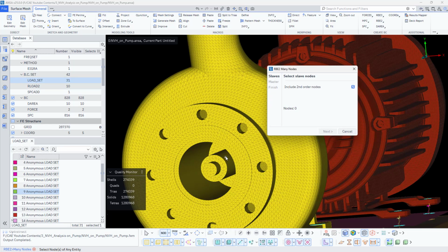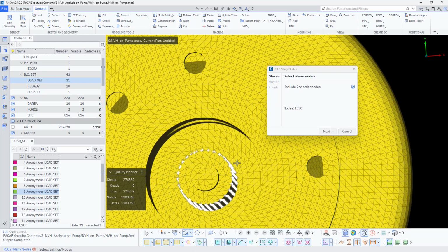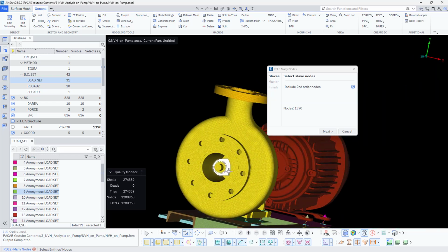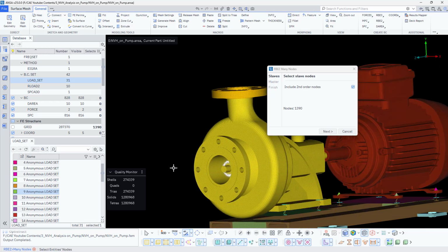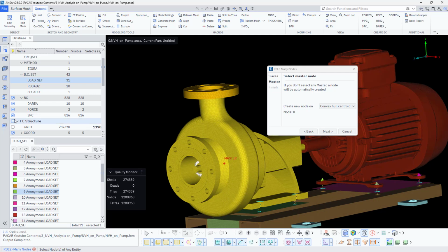Yeah. So now, as I said, that particular motor COG point is independent. So what I'll do is I'll just select this particular shaft as a reference for RBE2, and I'll connect this one to that, right? So this is one RBE2. You can even select the whole model and define it. That is also fine. If we do it, you might get stress hotspots, because the load will tend to consider only these grids and it will impact on it.